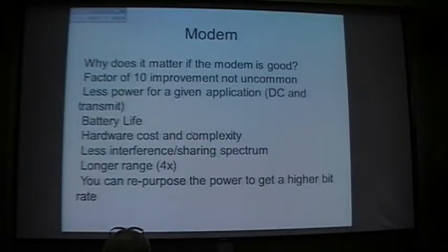A lot of the problems these days, in particular in commercial applications, with channel spacing getting smaller, the amount you transmit into adjacent channels, say through phase noise of your transmitter or other spurious emissions, that's reduced if you don't have to transmit as much power. There's also hardware costs. It costs a lot less to make an amplifier that's 10% of the power output of another one. And longer range if you use the same power.